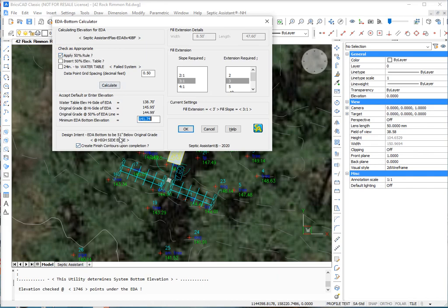And you see here, 51 inches below grade, 39 inches below grade. So this is a tool you can use to come up with the lowest grade to put the bed. And this number is adjustable. If you don't want to have it at 0.74, 0.75 is a much more reasonable number for the installer to use. We just enter that, and that changes that number.